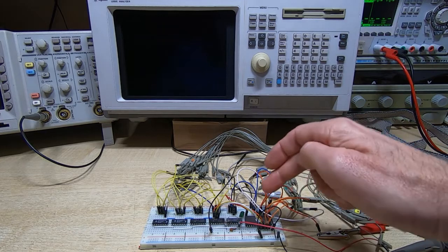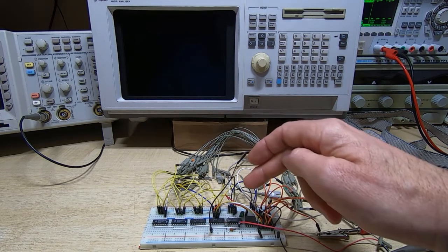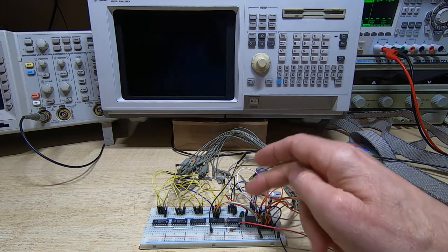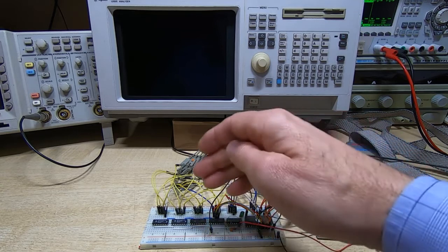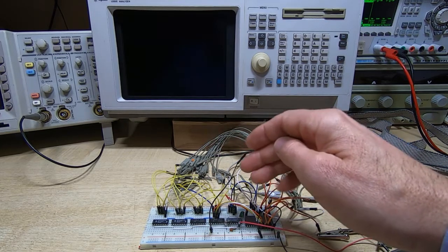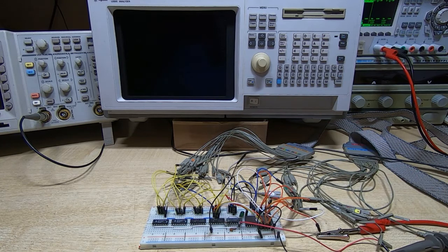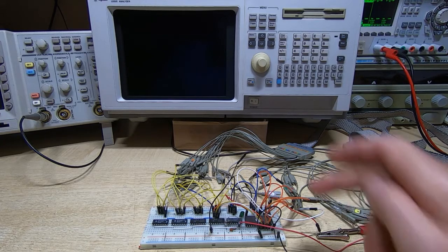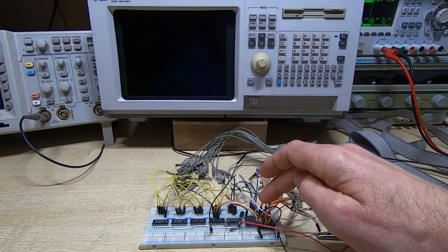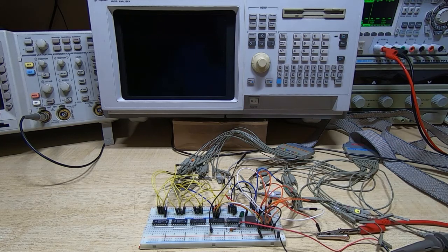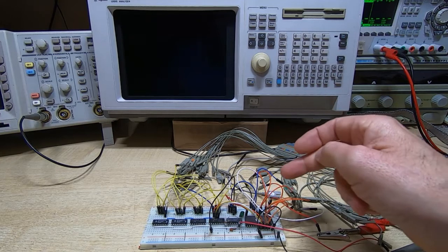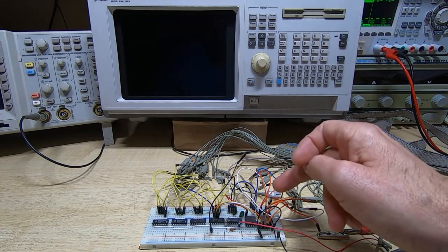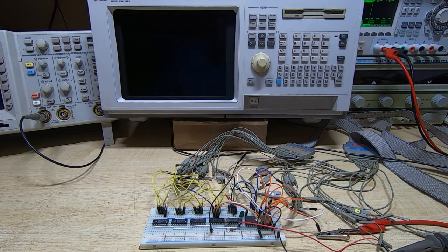So what I've got on this board is a ROM, a 16-bit synchronous counter, and a simple clock. The clock's running at about 1.5 megahertz, so it'll give us about a 20 millisecond cycle time for the counter, and that will give us a good cycle time for doing any testing that we want to. I've put some data bytes into the first 8 locations on the ROM, and the target for us in this video is to filter and display just the values in those 8 locations.